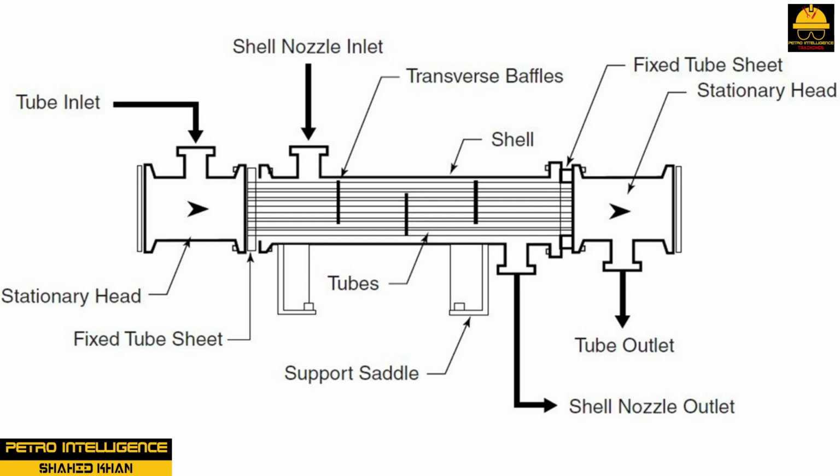Each tube sheet is a flat, metal disc that functions like a collar for the individual tubes. The tube sheets can be hollow or solid. The hollow design is for leakage protection. As flow enters the tubes, it experiences maximum heat transfer. Conductive heat transfer is at its highest where the tube sheet, shell, and tubes meet. By the time the tube flow exits the exchanger, very little, if any, heat transfer is taking place. The term single pass indicates that the tube side flow goes across the exchanger one time.